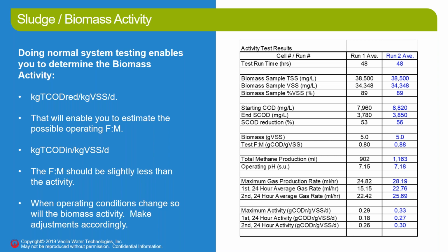And in that situation, it's likely that the acid formers will continue to work, but the methane formers won't be able to keep up, and you'll get your system to a point where it's not stable, and the volatile fatty acids in your effluent will be very high, which we all know is a bad thing.